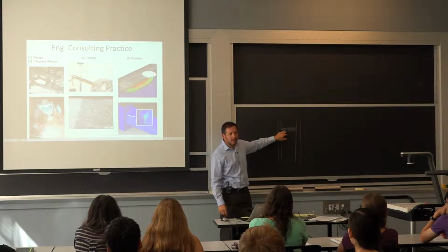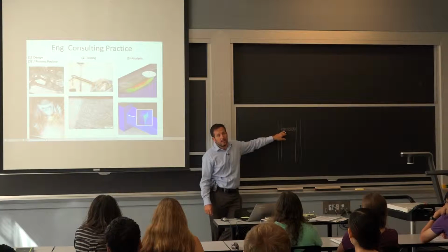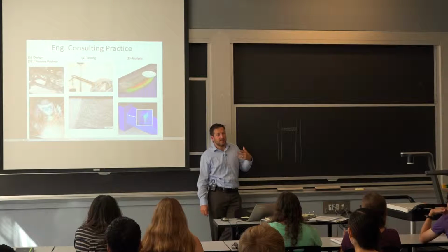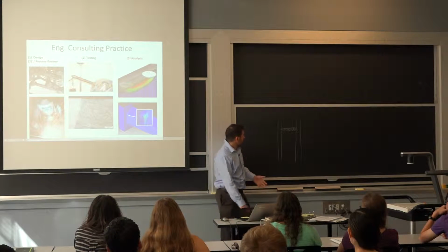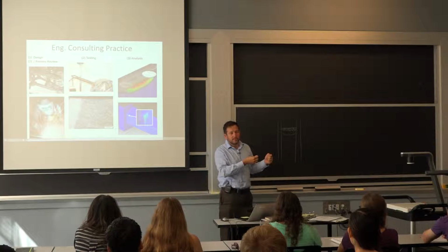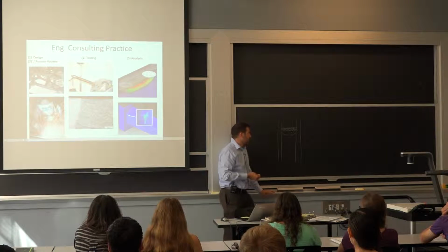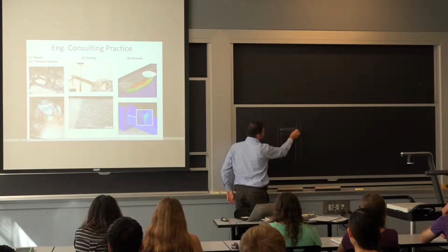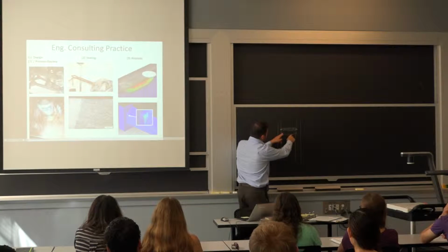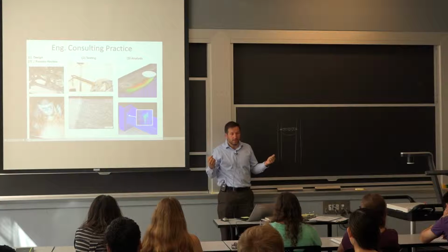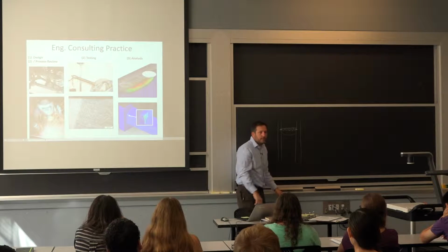So that steel got heated very quickly during the fire. And it wasn't a question of getting it to a melting point. It just had to become soft enough that it started to deform and become a little bit like a rope. And it pulled on the columns. So at least the NIST study points to this effect, there was a very good connection between the floor joist and the column. So when it started deforming and bending, essentially the entire joist shrinks in length and pulls. It pulls on each side, just like if I'm hanging clothes on a clothesline.